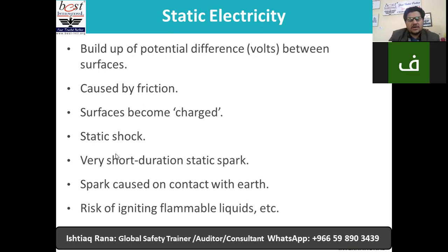And if you don't have bonding or earthing, we call it grounding as well, though in that case, to avoid static electricity, bonding is more preferred and logically, technically more sound. But what if that is not there? So more chances of fire, more chances of explosion, and several incidents happen. Sometimes bonding is also there, but non-functional. It didn't work actually. So it's a build-up of potential difference, like volts, between surfaces.